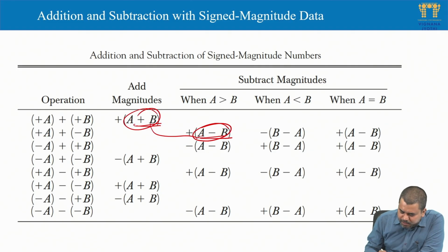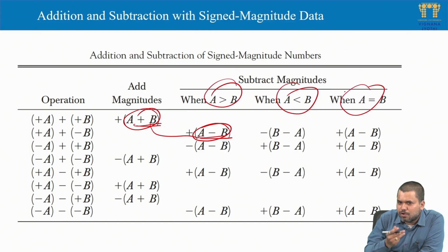Instead of the comparator, we can use the same 2's complement subtraction and decide whether a is less than b or a is greater than or equal to b based on the end carry. Using 2's complement subtraction by the addition method, we can avoid the use of the comparator. Also, we can use one XOR gate.